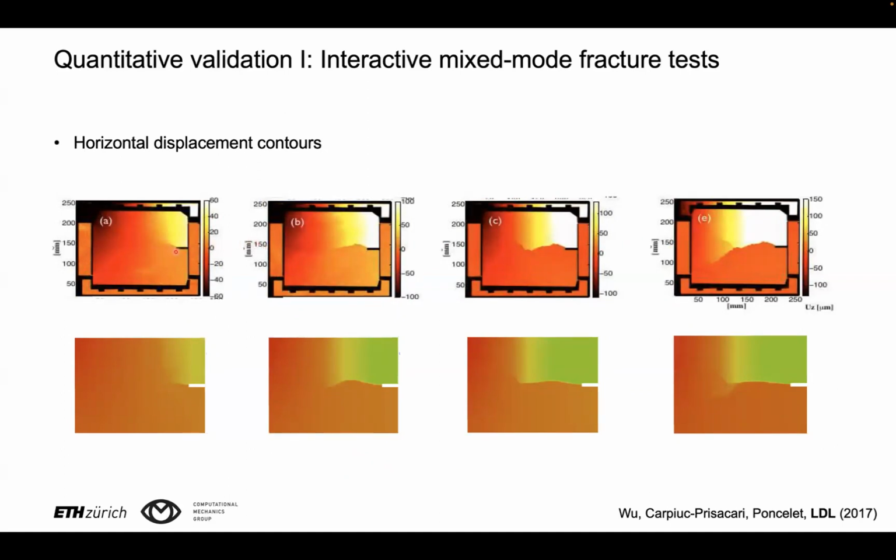And you see here that as a result of the complicated and stable loading history, the crack first stably propagates upwards, then at some point it changes direction and starts propagating downward. And then at some point, again, it changes direction and starts propagating upwards until, shortly before failure, it branches into 2 branches having different directions.